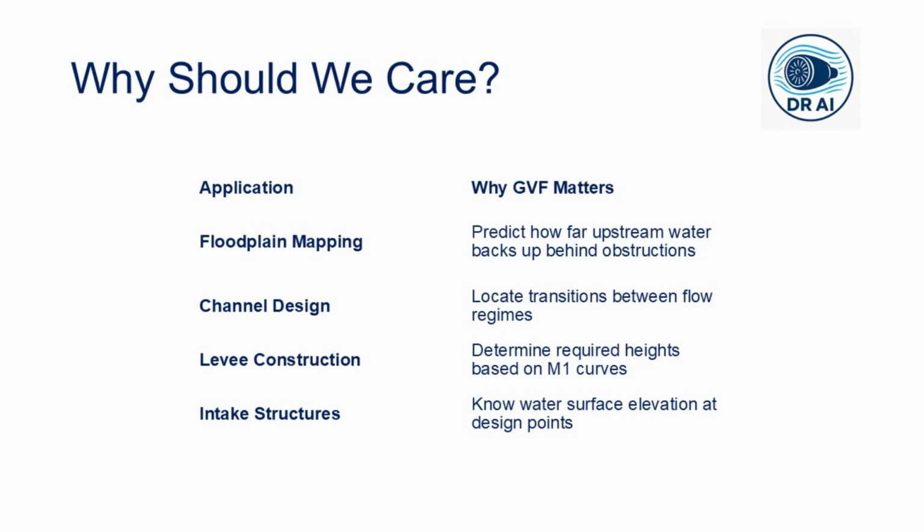events. The second one is channel design. If we are designing a channel that changes its slope, say from a steep section to a mild section, we need to know where the transition between flow regimes will occur. Will a hydraulic jump form? If so, where will it form? This is crucial for lining the channel to prevent erosion.